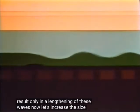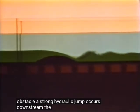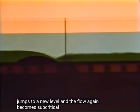Now let's increase the size of the obstacle. A strong hydraulic jump occurs downstream. The upstream subcritical flow changes to supercritical as it passes over the barrier. Further downstream, it jumps to a new level, and the flow again becomes subcritical. Look upstream as this flow begins. Notice the strong blocking effect.